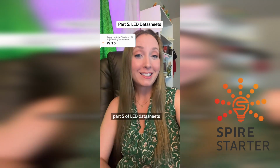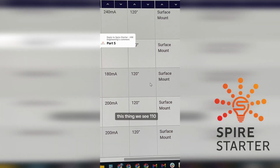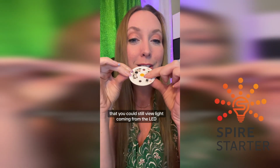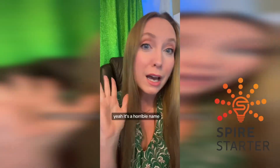Part 5 of LED Datasheets, and we left off at viewing angle. This thing, we see 110, 120, 115. What does it mean? If you thought it was the largest angle that you could still view light coming from the LED, you'd be wrong. Yeah, it's a horrible name.